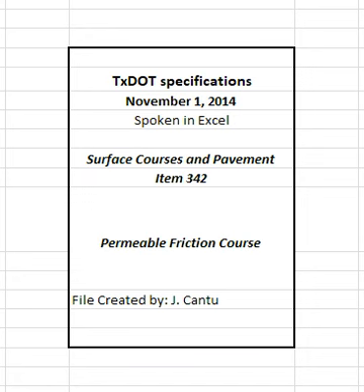4.4.2.2 Engineer's responsibilities. 4.4.2.2.1 Gyratory compactor. The engineer will use a department SGC calibrated in accordance with Tex-241-F to mold samples for laboratory mixture design verification. For molding trial batch and production specimens, the engineer will use the contractor-provided SGC at the field laboratory or provide and use a department SGC at an alternate location. The engineer will make the contractor-provided SGC in the department field laboratory available to the contractor for molding verification samples.